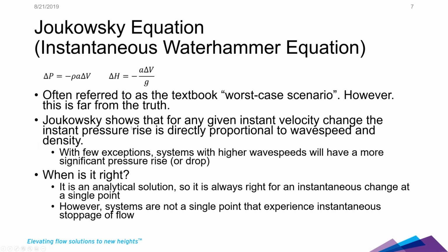Joukowsky is often referred to as textbook worst case. It's far from the truth. Joukowsky shows that for any given instant velocity change, the instant pressure rise is directly proportional to wave speed and density. So with few exceptions, systems with higher wave speeds will have a more significant pressure rise or drop. So you can think about that for pump trips.